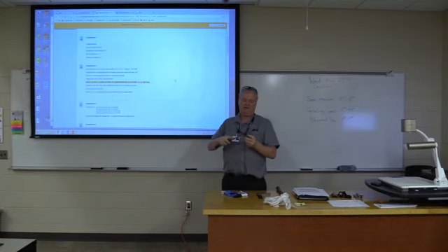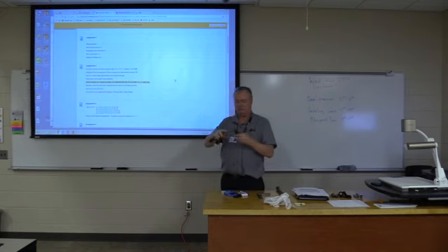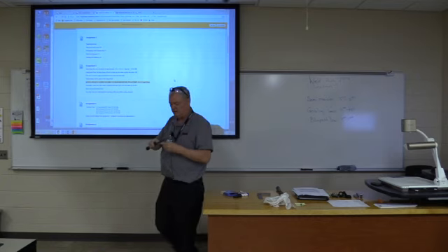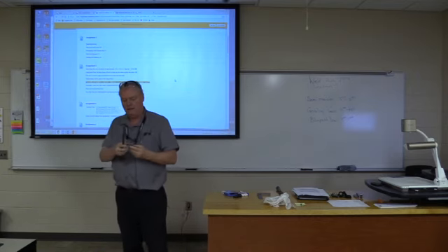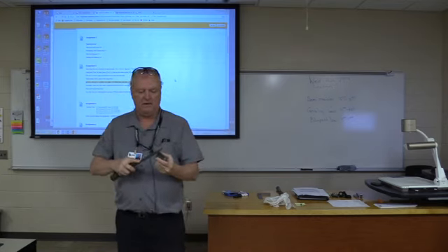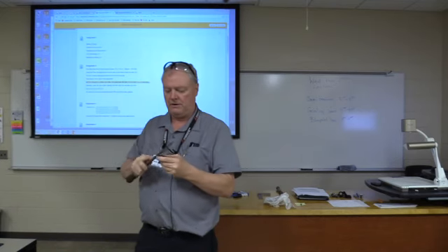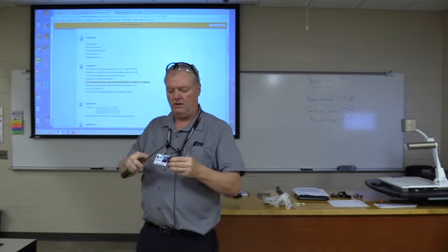So your technique is basically you're going to be filing the part, and all I'm doing is holding it in my hand, sliding the file up and across the edge as I go. I'll come a little closer to the lens over here. And what I'm doing is I'm taking off the burr on all of my edges.